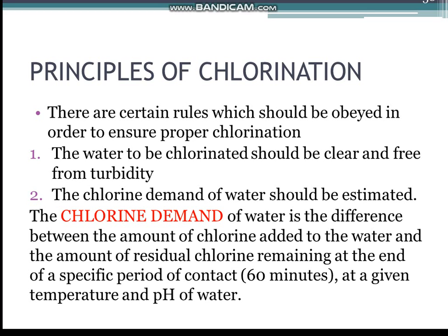Second, the chlorine demand of water should be estimated. Now, what is the chlorine demand of water? It is the difference between the amount of chlorine added to the water and the amount of residual chlorine remaining at the end of a specific period of contact, usually 60 minutes at a given temperature and pH of the water.